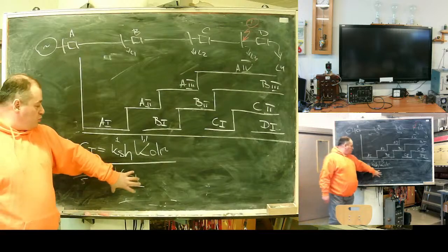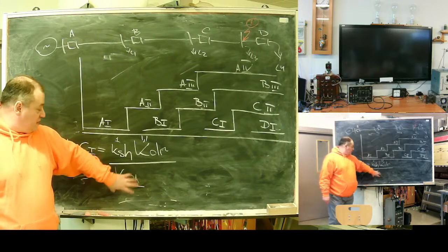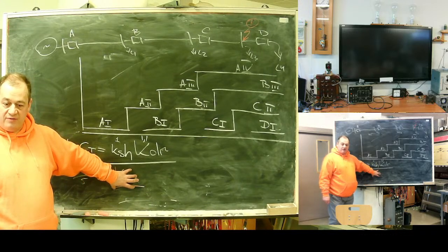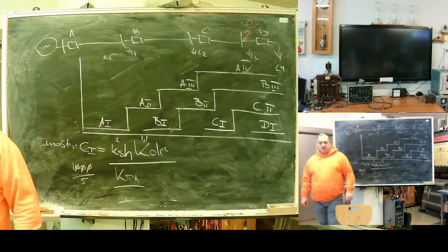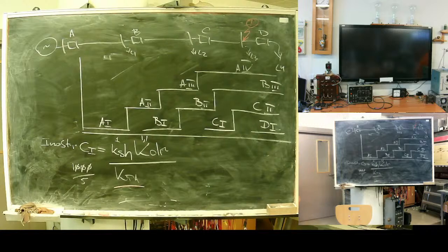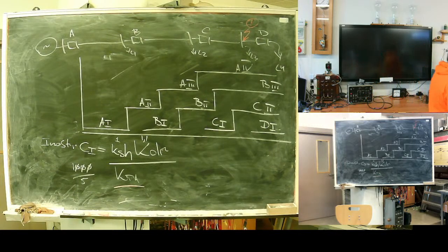So you do not take this into account when you calculate settings, but you need to program it into your relay as a separate element in the settings table, and the relay will divide for you.